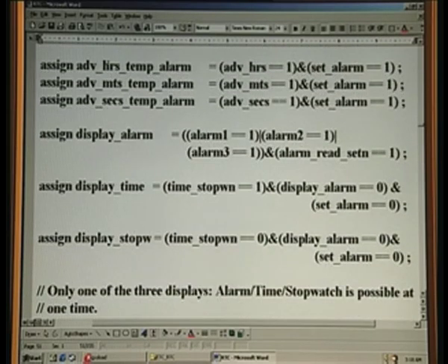And this is precisely the same for minutes and seconds as well, this is self explanatory. And next, we have what is called display underscore alarm. In the simplified architecture, we have seen this, this is what I had shown there, and what all it means is you want to display just the alarm you want to set or read the alarm back, okay. You have 3 different alarms, for example, alarm 1, 2 and 3. If one of them is set, this is basically a debounce switch. There are 3 switches for alarm 1, 2, 3. This is nothing other than a debounced input, right?